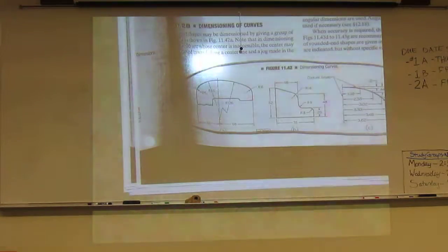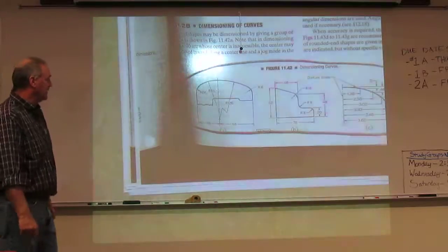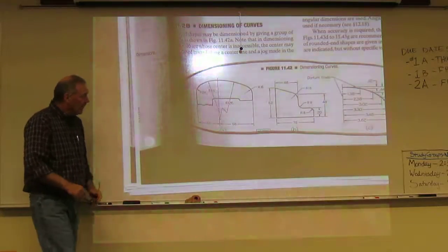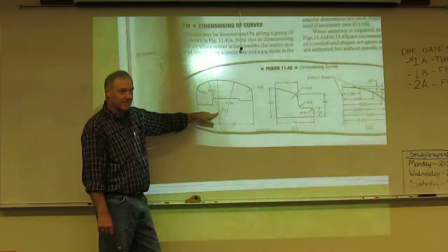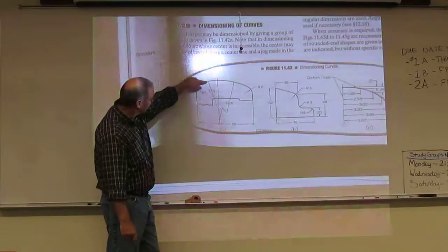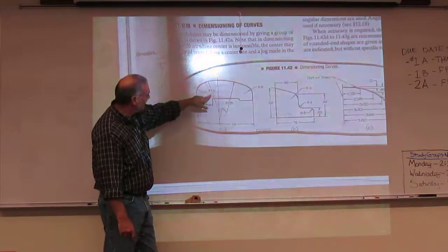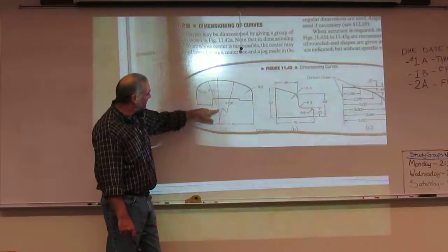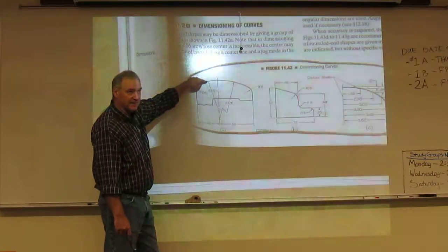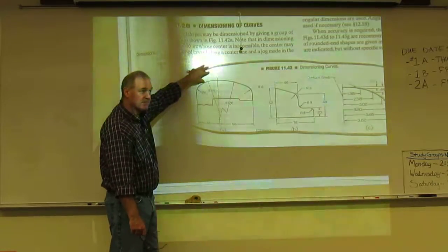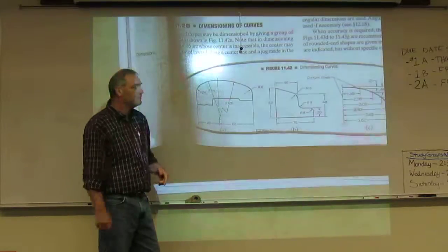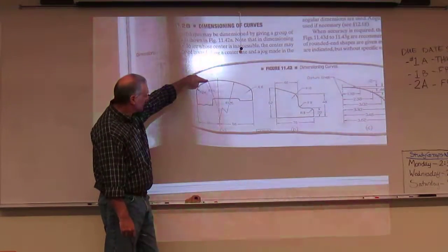So radius. Now here we're doing cylinders, but they're partial cylinders, right? And again, they can be positive, they can be negative, depending on what the case might be. Our preferred way is to have a tick mark on a radius or an arc. We bring the center line or the leader line up, we put our dimensional information inside of that line, arrows on the inside. Now, technically, I would really want this number off of the object, because I want to keep this out of it. But that's going to get that.